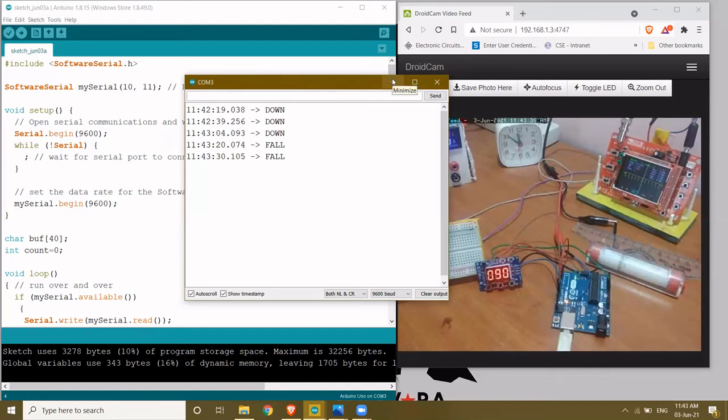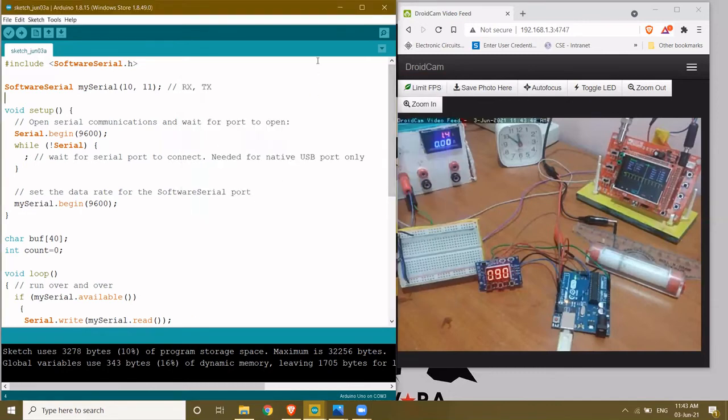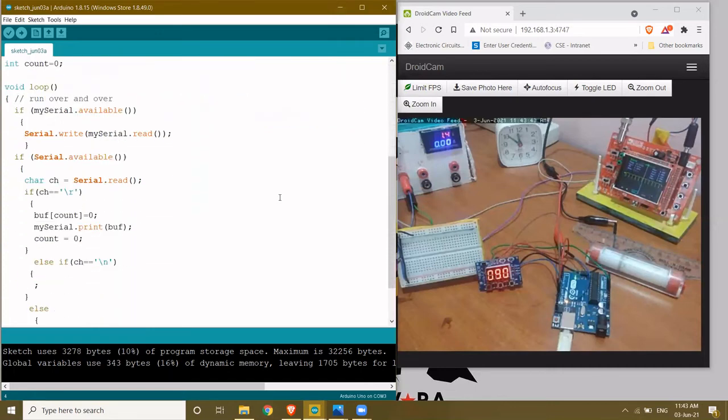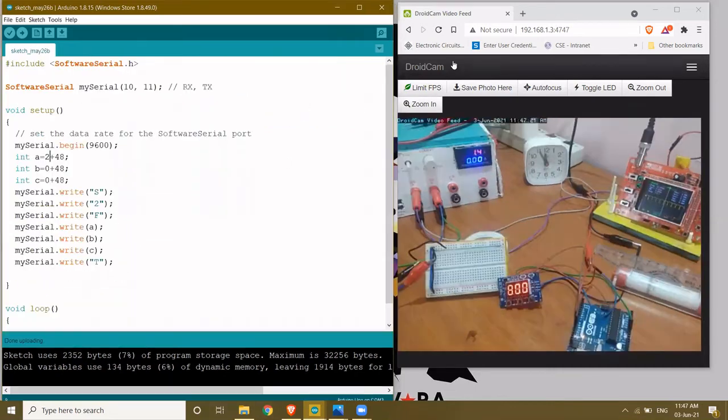But if you want to use any potentiometer or encoder to vary this, you can modify this program. But I also have a simple alternate program to vary the parameters of this module. Since the module accepts only data in the form of ASCII, we have to send everything as ASCII values. Since serial communication in Arduino sends data as ASCII by default when we include it in double quotes, there's no problem in doing it.